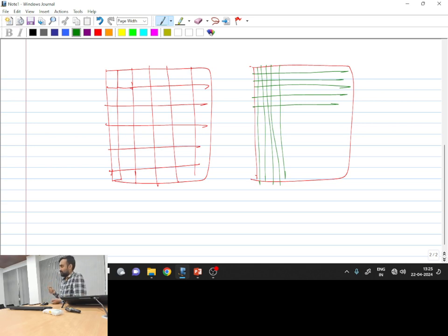Okay, so it means that whenever you do the PIV measurements, it is not only that you have captured the images. Once you have captured the images, you have images in raw form, then you have to select different values of delta x, delta y and delta t, and then you have to see for what values you are getting convergence. Because if you choose very large delta x, delta y, then multiple regions may have chances of getting a match.